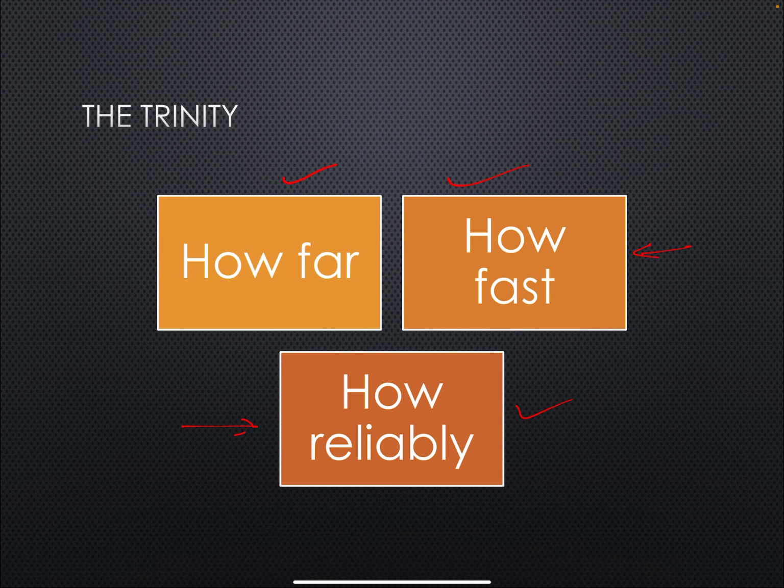In analog systems, this is given by the signal to noise ratio. In digital systems, because the information is binary, bit error rate is a more commonly used specification. Again, how reliably the information is received is determined by the noise of the receiver and maybe even transmit noise.